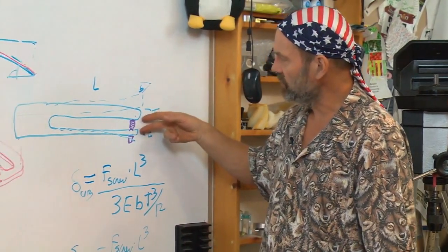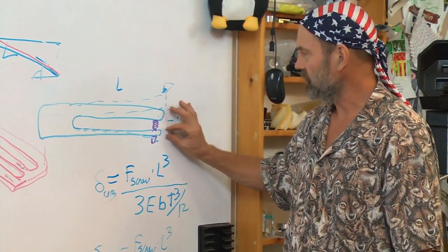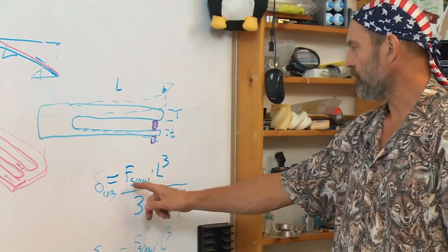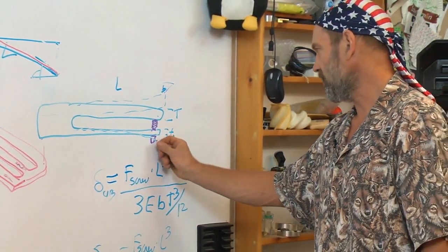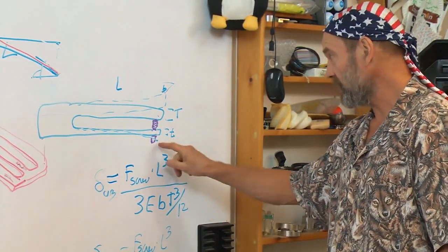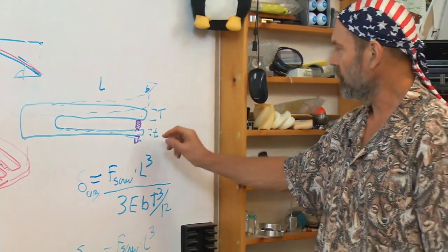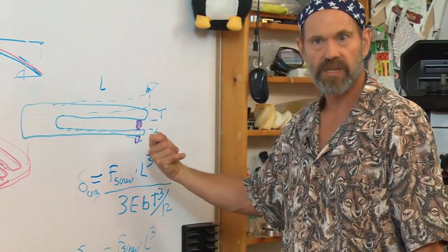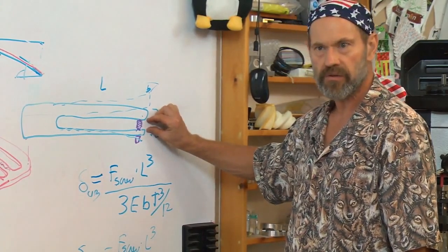So what does that tell you about what happens with the upper beam with respect to the lower beam? Well, when you apply the screw, you never really apply a force so much as a displacement. When I'm adjusting this thing, I'm applying a displacement to the screw. For example, one turn of the screw, if the screw has a pitch of 1 millimeter, means the screw will lengthen by 1 millimeter.